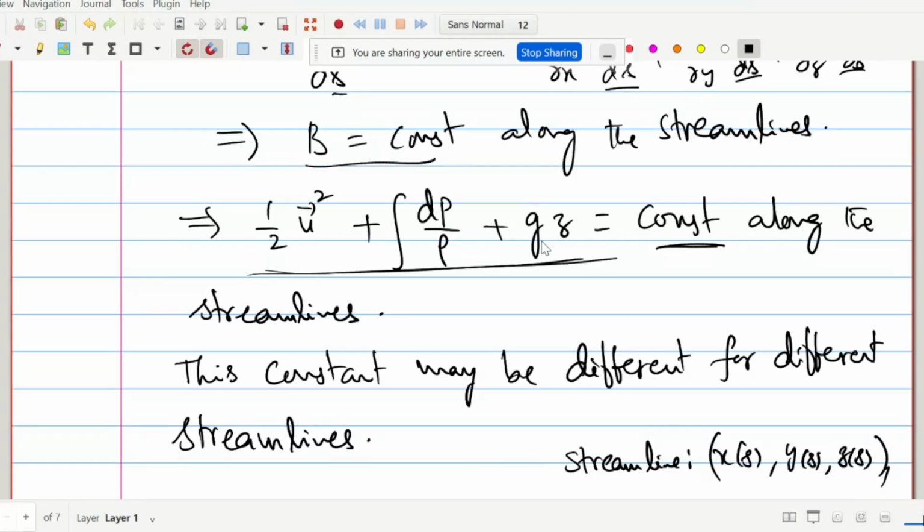So z equal to eta of x, y, t, that is, z minus eta of x, y, t equal to 0. So you derived some kinematic condition because there is another unknown coming into the picture, right? That is your eta, the surface elevation. Along with this, whatever you integrated, the momentum equation, that is considered as the dynamic boundary condition. So the kinematic condition and the dynamic boundary condition, coming from this integrated Bernoulli equation involving phi, that is how you solve the water wave problem.